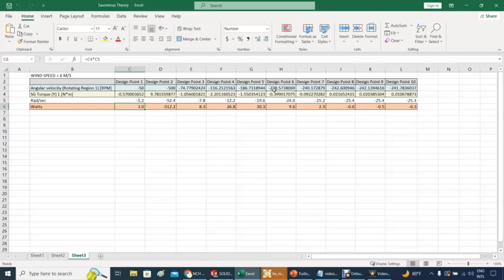And as you start to increase the RPM of the turbine, then obviously the amount of energy extraction will be less and less until almost nothing. So here's, I would say, the sweet spot to get as much energy as you can produce, which is not much. It's predicting a number around, I would say, at the best 30 watts. But again, wind speed is a breeze. I'm not talking about anything faster.